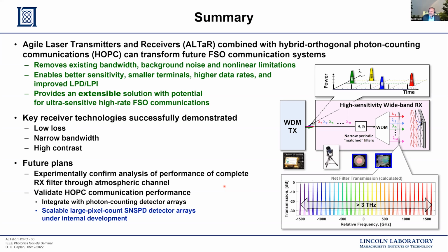Okay, so I think this gets to the photon counting detector. Initially we were envisioning, and a lot of my analysis was assuming, detector technologies that are readily available. So the LLCD system, which was fielded in the 2013 timeframe, used these SNSPD detectors, these superconducting nanowire detectors. Their effective bandwidth is on the order of a few gigahertz, so their dead time is relatively short.